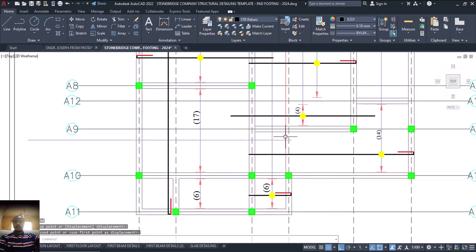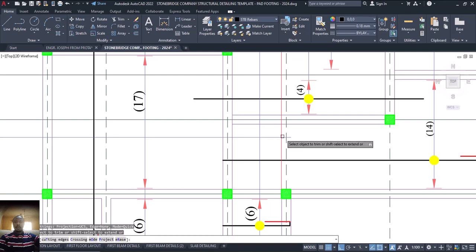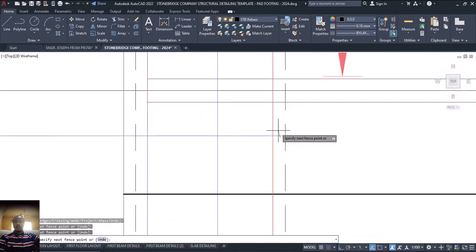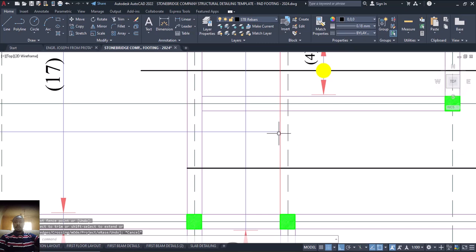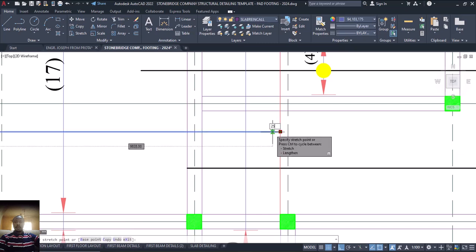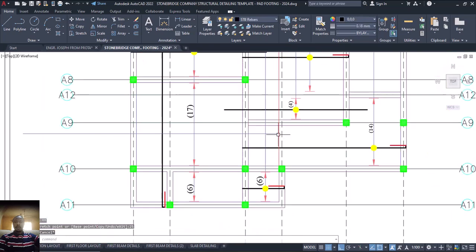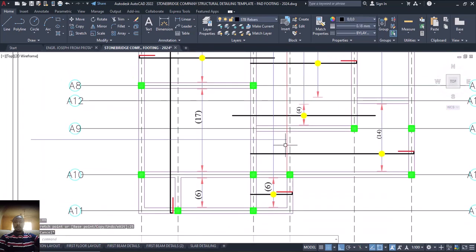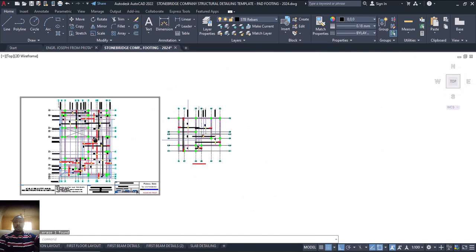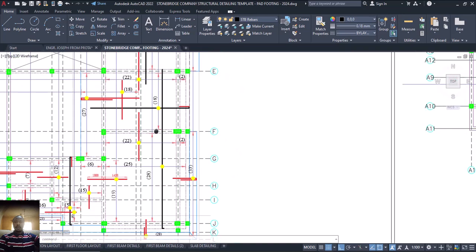Okay, that's fine. So now come to this TR, enter. That's trim. Now let me have my offset of 25. That's 25, right? Is that okay? Enter. Okay, that's fine. So I can now come to this place, remove this line, I'm done with it. So I'll now come to this place where I have the sample of that.